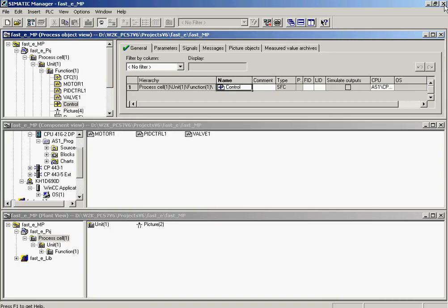This is a very simple application to illustrate the power and ease of use of the SFC editor. Real sequential control operations can be far more complex. For example, it is typically recommended to include an evaluation of the feedback signals within the transition conditions.